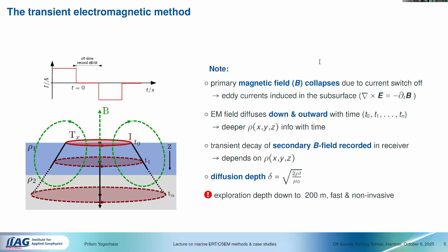So you can easily reach target depths of maybe 200 meters, depending on your source field, depending on how long you record, depending on the subsurface resistivity. You can also downsize the equipment if you want to go for the very shallow zone, to very small, handy equipment, then you can sense maybe the upper 20 meters. You have very strong limitations to do experiments resolving, let's say, the upper 5 meters.